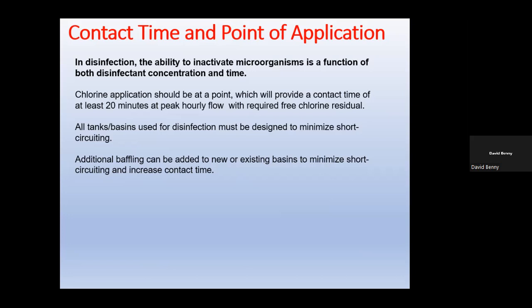But the concept is you must have a detention time, and the tank where you put in the disinfectant must be baffled to minimize short circuiting. If you want to reduce the time, you remove baffles, and if you want to increase it and make sure it's effective, you increase the baffles.